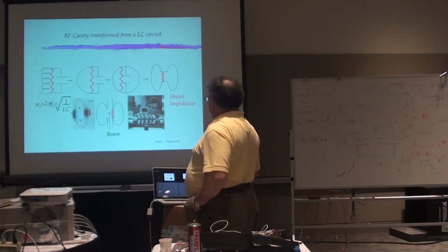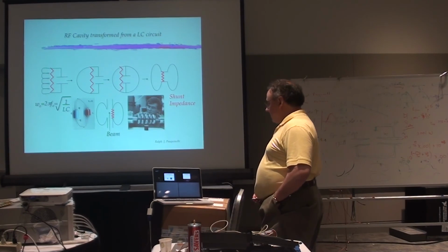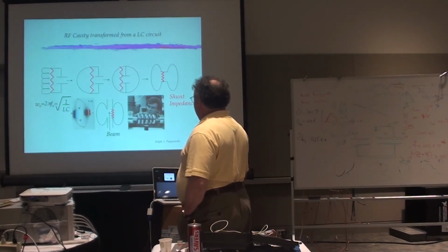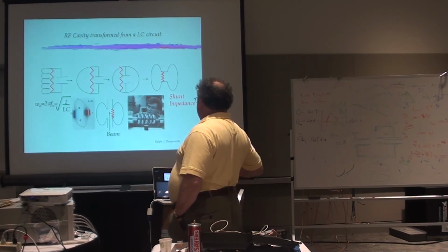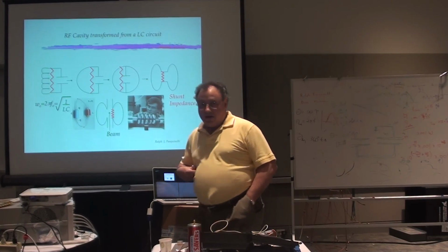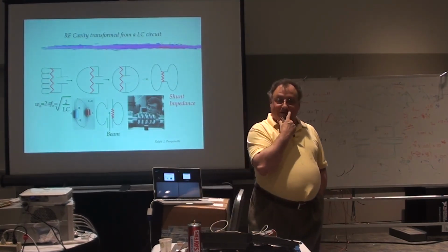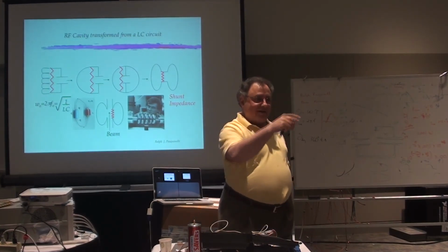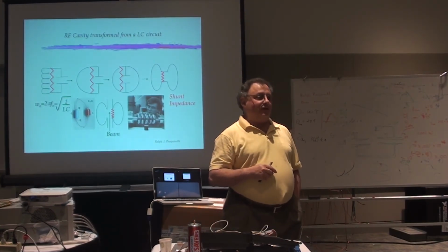Okay, but of course no cavity is perfect. Even superconducting cavities have a certain amount of residual impedance, and so you have this shunt impedance across any kind of cavity you could possibly make. The difference is in a low frequency cavity. This cavity is 805 megahertz. Some of you have started to measure it, and the one on that table has a Q of about 700.